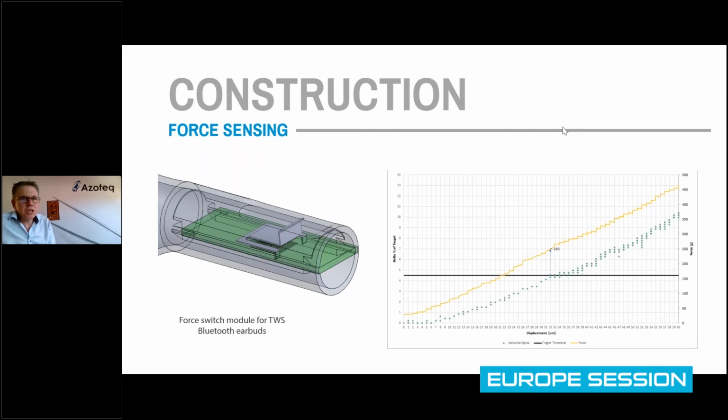And then there's normally a tuning capacitor. You want to get the coil to its resonant frequency, so after you've made your PCB design, which you believe is the best you can, then it's a little bit of experimentation, trying two or three different capacitors to get your coil to the resonant frequency.